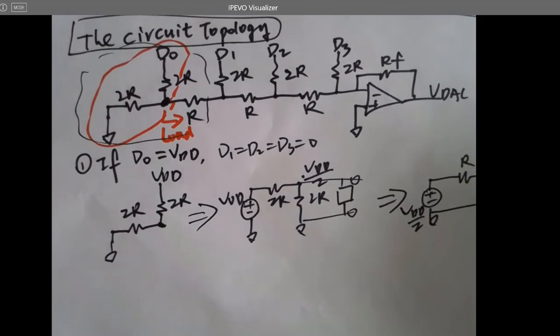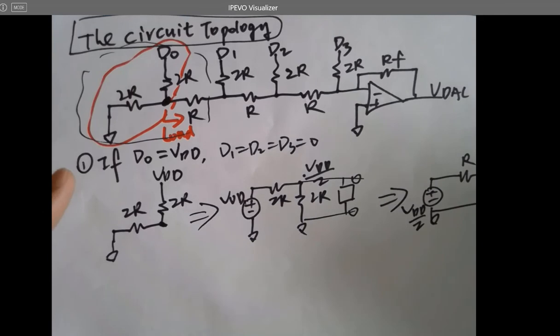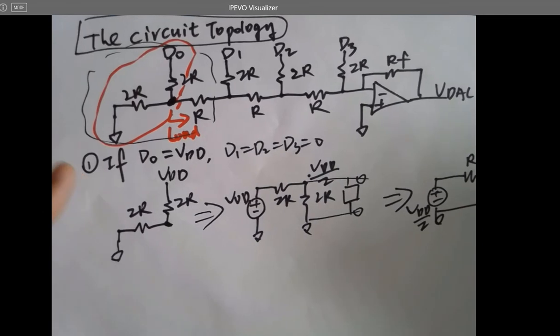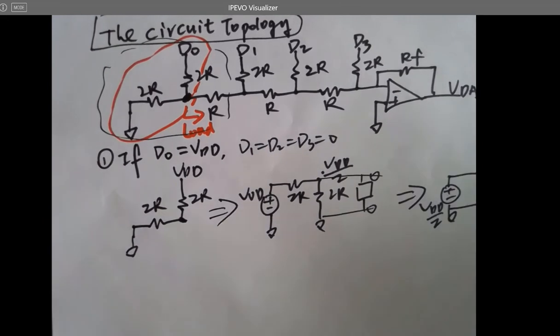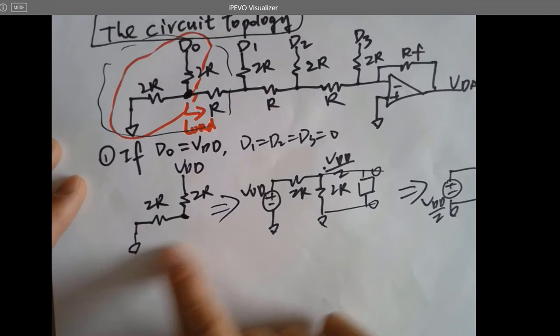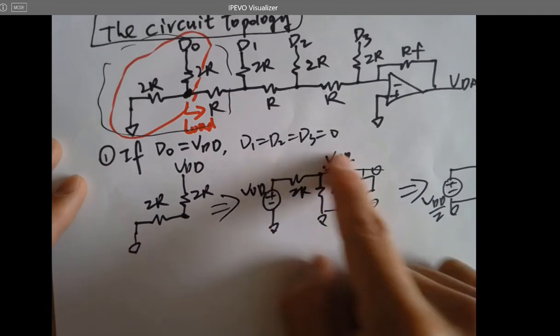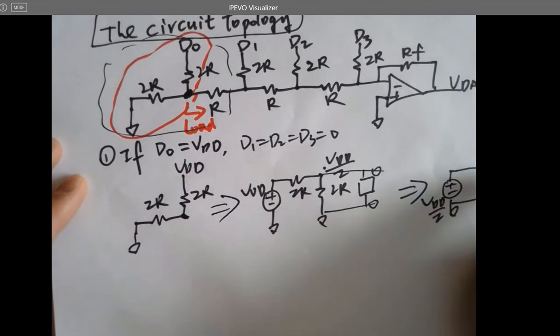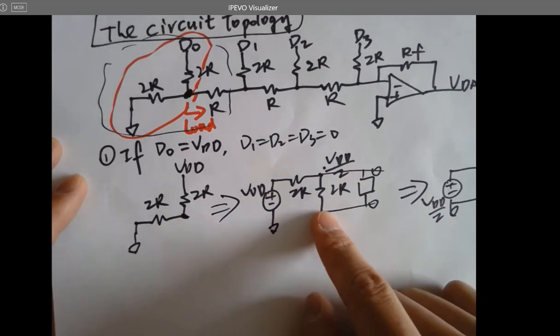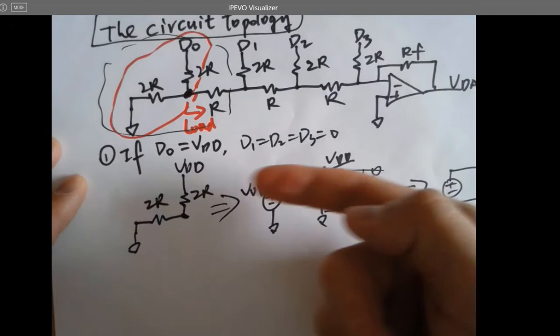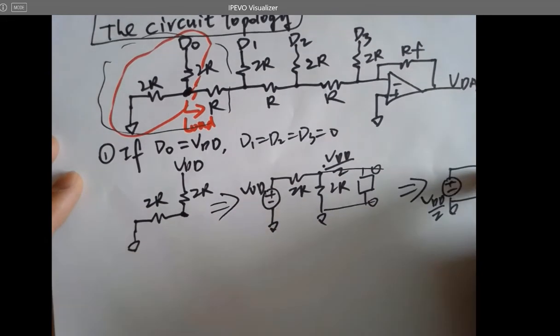So when you are doing the Thevenin's equivalent circuit analysis, one entire lab yesterday is still not enough to let you be familiar with Thevenin's equivalent. No worries, it's not hard. Just watch the videos and it shouldn't be difficult. So that's the circuit. You can convert it into the Thevenin's equivalent, and here's a load, which is going to be VDD over 2, which is ETH, because that's a voltage divider.